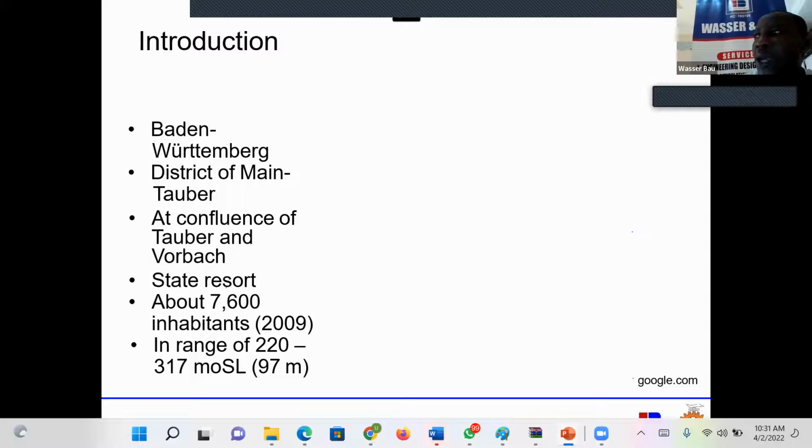Safety factor that will take care of population explosion, which we're having now, change in demand, change in land use, water losses, which stands at 40% today in Abuja. Yes, 40% of the water produced from Lower Usman Dam is lost. And then other design inadequacies.